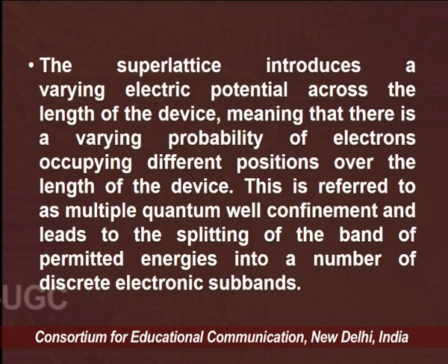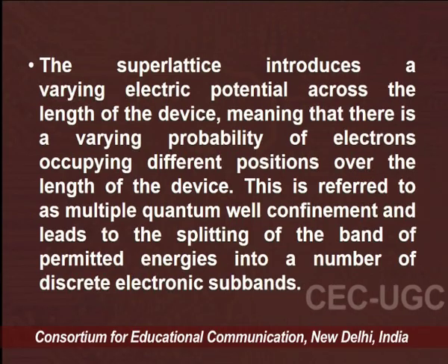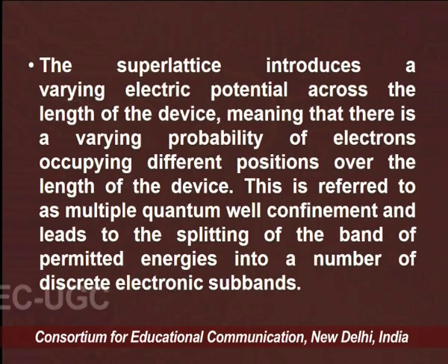This is referred to as multiple quantum well confinement and leads to the splitting of the band of permitted energies into a number of discrete electronic subbands.